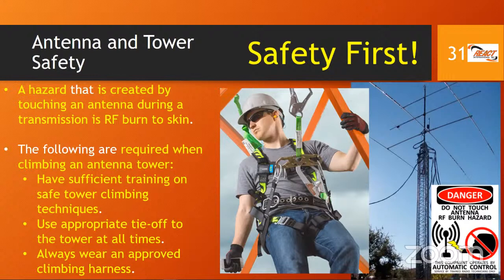But also, we need to be aware of our radio frequency transmission. We have our antenna here, and we are transmitting using our radio. It has power going to that radio, and there are voltages and currents leaving the radio and going to the antenna. So there's something called radio frequency burn. If you were to touch an antenna while someone is transmitting, you might get burnt. It's an RF burn, right? Radio frequency burn. And that's not a nice burn at all to have.